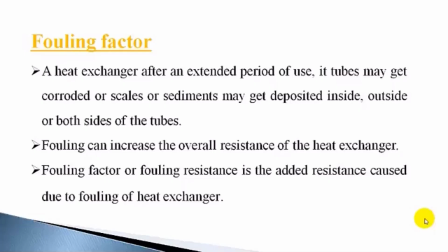So fouling is a process of a heat exchanger. After an extended period of use, its tubes may get corroded, or scales or sediments may get deposited inside or outside or both sides of the tubes, and this is known as fouling. The result of fouling is to increase the overall resistance of the heat exchanger.